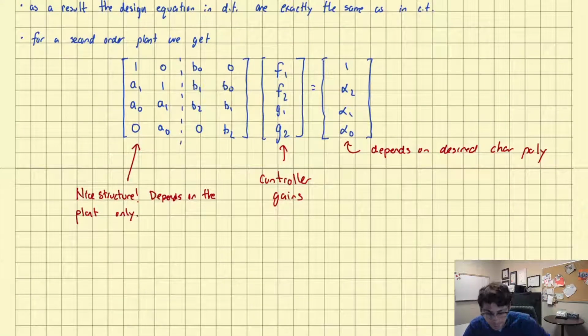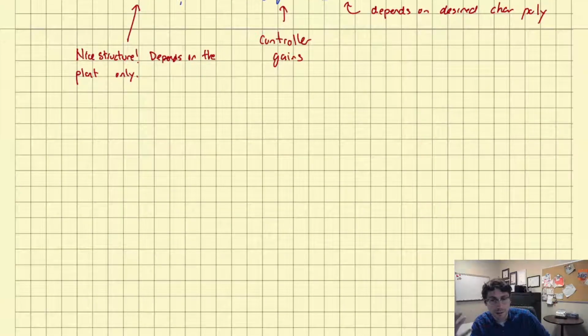Okay. So everything is similar to continuous time. And this equation will have a unique solution if and only if the plant numerator and the plant denominator do not have any common roots. Which, of course, if you're dealing with a transfer function, you will always see it that way. You'll always get it in reduced form. The only time that might be relevant is if you generate the denominator and the numerator polynomial separately using state space methods. Then, of course, they might not be coprime, but if you're given a transfer function, it will be coprime for the most part. Okay. All of the caveats that we have made in continuous time and that you've seen in the labs apply in discrete time as well.